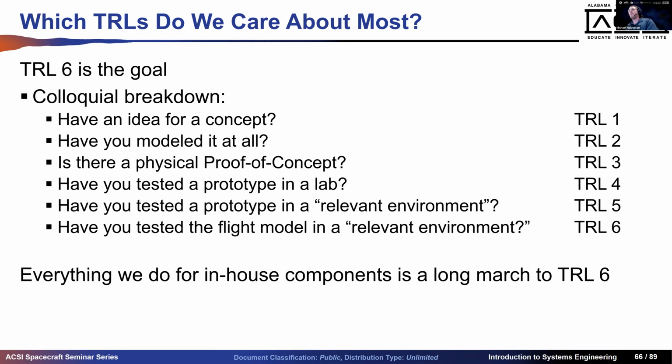You're testing it at minus 30 degrees C to plus 60 degrees C. That's a big temperature range, but you hear the difference between TRL 5, 0 degrees C, and TRL 6, negative 30 to plus 60. TRL 6 qualification testing is defining the operation within the bounds, the absolute extremes of the system operation.